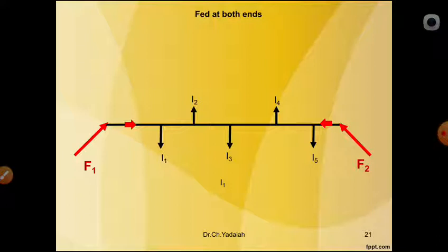A tube light requires some 230 volts. Due to the long load, that is a long distributor, the voltage drop may be more. At the starting we have 230 volts, but after going to the extreme right, the voltage may not be 230, it may be 200 or 180 volts. Then single phase motors may not work properly at low voltage.